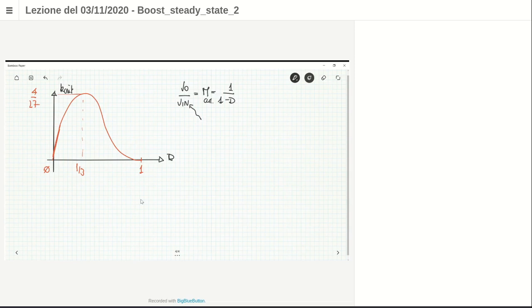So typical specifications give you the minimum and the maximum input voltage, while the output voltage is always constant. Right? It is my DC output quantity I have to get. So when you know this variation, then you can also have a measure of your duty cycle variation. Okay, so the duty cycle, inverting this kind of expression in terms of D, is simply V0 minus Vin divided by V0.